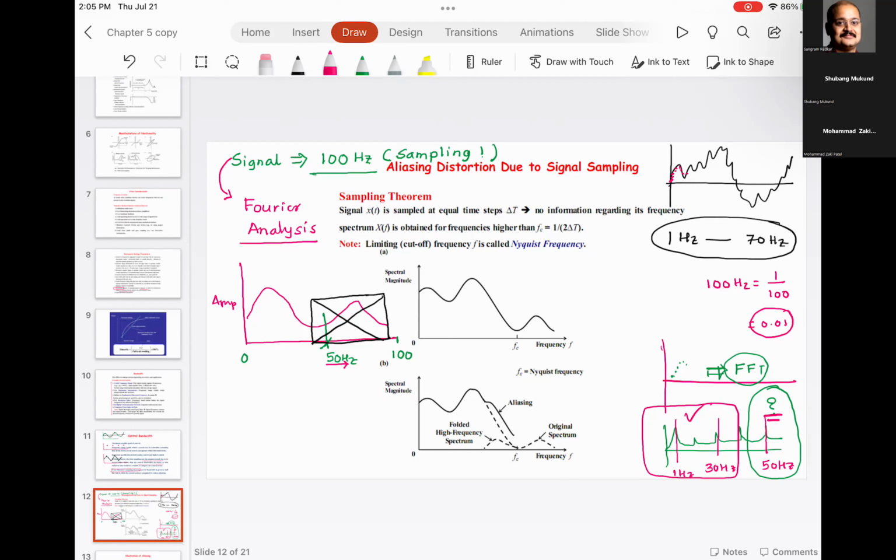So aliasing is super duper important, and you see that many times in industrial applications. Whenever somebody asks you to understand or simulate or investigate a power spectrum, make sure that aliasing is not hampering your result. So how do we minimize aliasing?